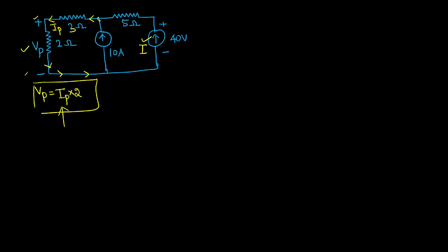Okay. So I'm selecting this node. I'm calling this voltage Vx. According to nodal analysis, the selected node is the superior one, and that will deliver the current for the entire circuit. Alright, so we have to take it like this. Let me take I1, I2, I3. So while applying nodal analysis, step number one, we have to apply Kirchhoff's current law.